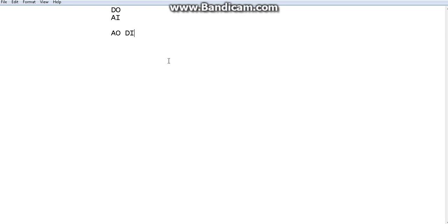So let's see a small thing before we get into the next step. We know 5 volts is getting divided into 1024 units, and we subtract 1 because we start from 0. I'm sorry guys, so we end up at 1023. So in other words, 5 volts is 1024 units.